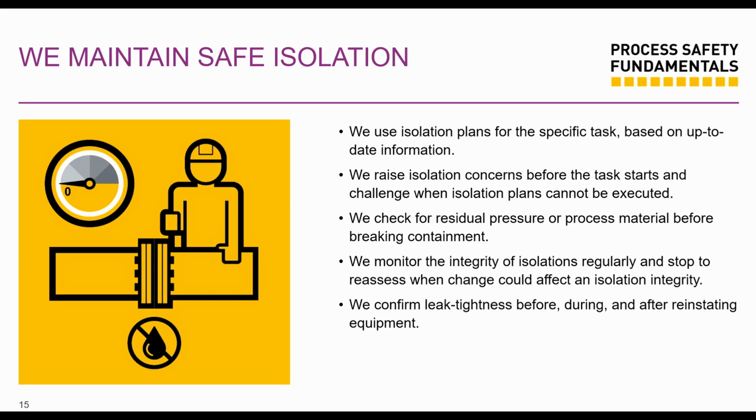And then, with your double block and bleeds, or a bleed in place, check if there's residual pressure in the system, or process material. Before breaking that containment, breaking that flange, opening that isolation valve or that strainer, or going into that vessel, we want to make sure that there's no residual pressure. Everything has been drained out, and there's no stored energy.